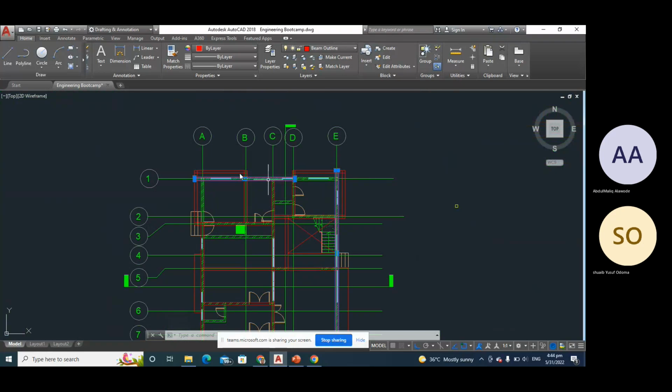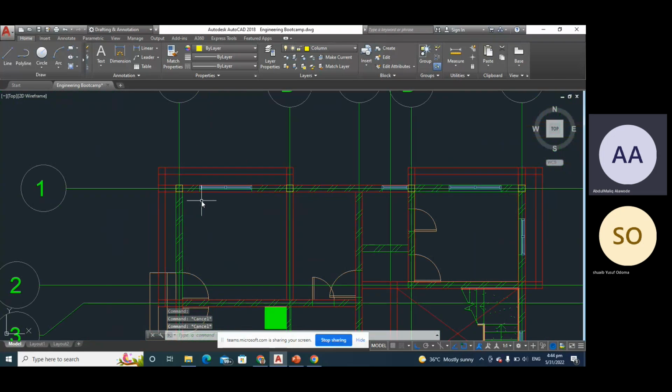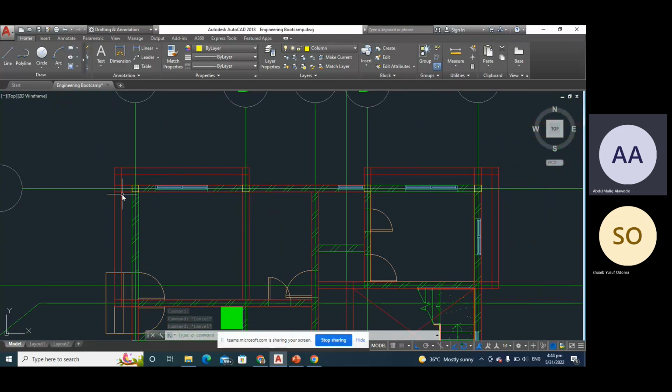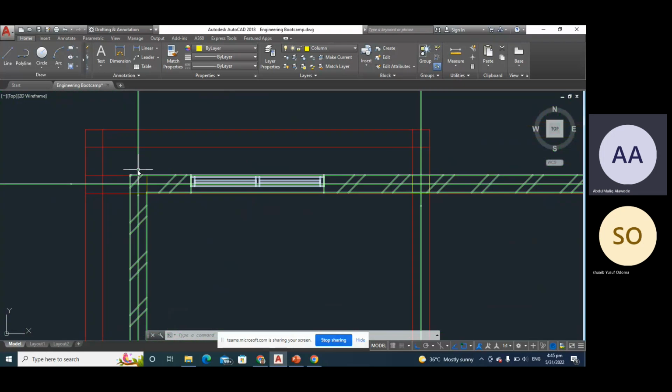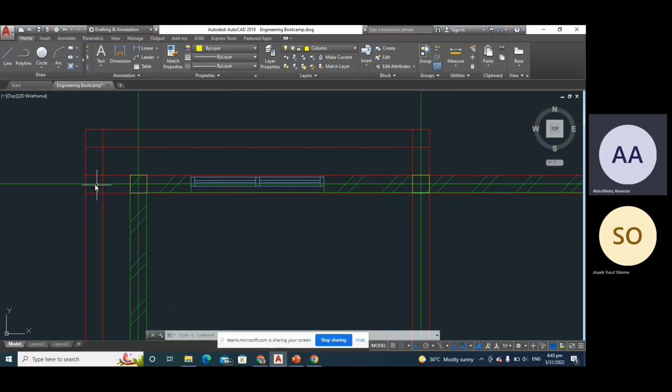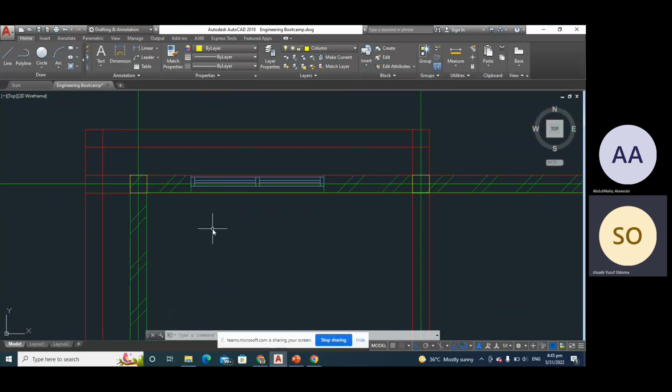Yeah. Now, if I get your question right, I've placed them here. Remember, I said we might later need to plant a column at this point or at this point, to support the roof, right? So the reason why I'm placing my column at this point is to have a column closer to the cantilever. It is going to reduce the load and the resulting moment from this cantilever on the beam. Do you understand? Yeah.